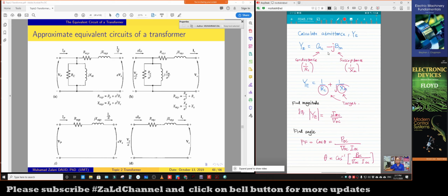So basically our target is to calculate the admittance. Alright, this is similar to what I explained earlier: YE is actually GC minus jBM. Why is that minus? Because earlier it was 1 over jXM, so this part is BM.